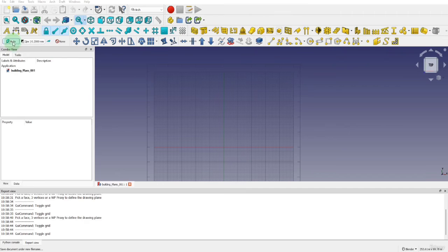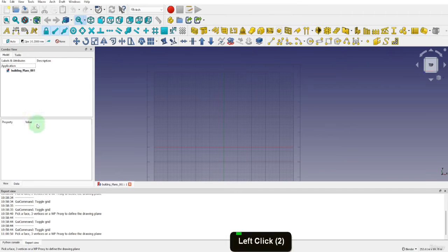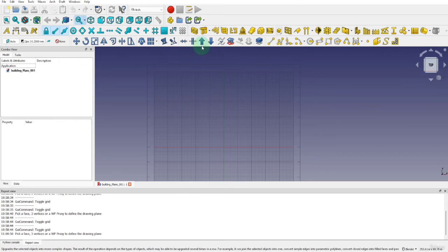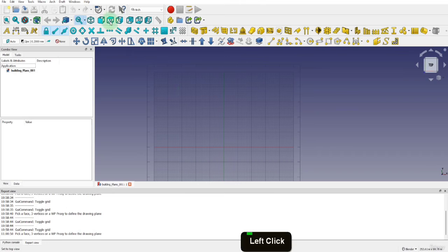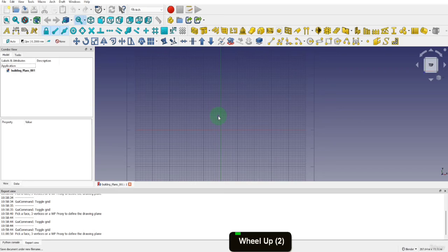To begin, we can make sure the working plane is set to auto. After changing the icon size, I needed to rearrange the toolbars here so everything was visible. Let's come into a top view. We're going to start with construction lines. These will be used for distance and positions. The construction folder can be hidden at the end of the process. So let's click and enable construction mode first. Now, any new object created will get added into the construction folder. That folder gets created as soon as we create something.